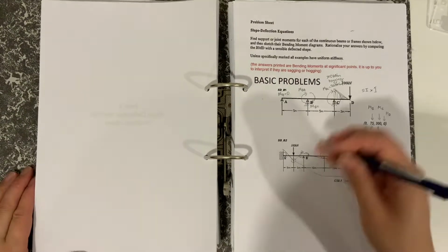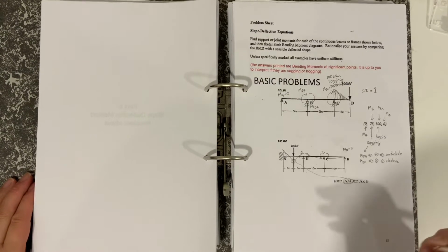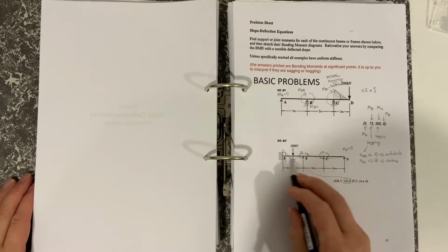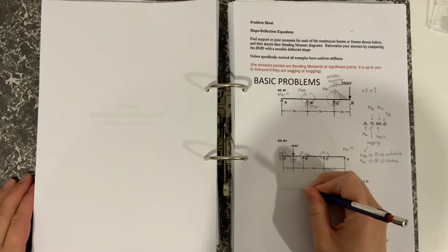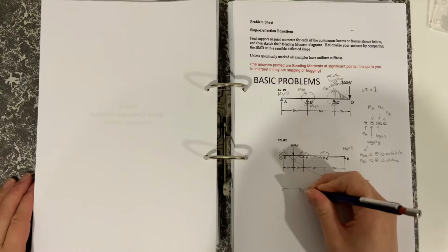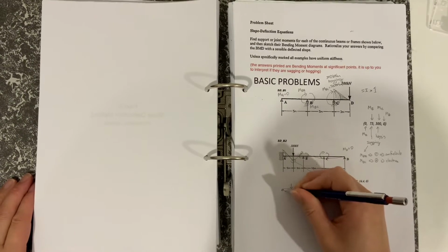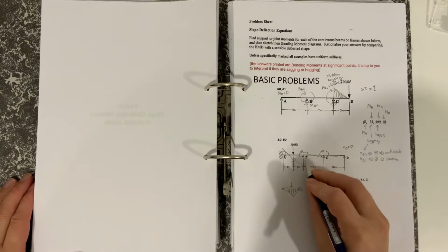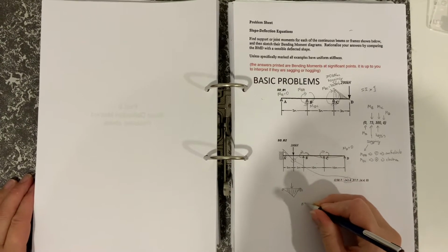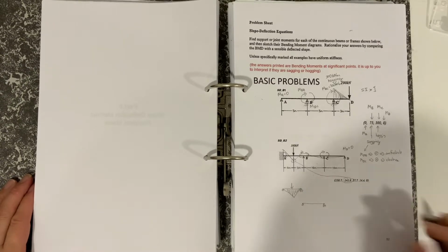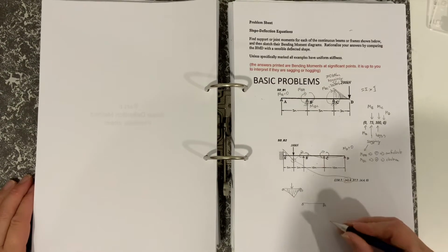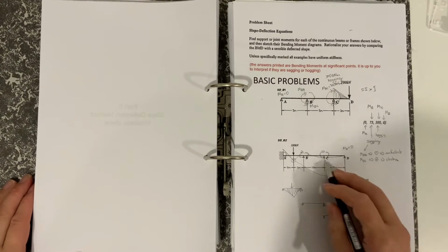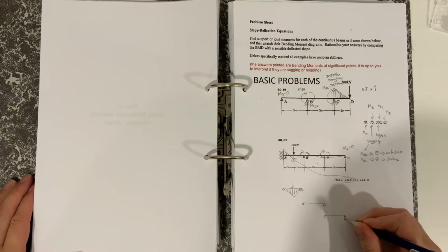So when you do the calculation, it might say what is the active bending moment diagram. So the active bending moment diagram for AB is, so that would be the active bending moment diagram for AB, and the active bending moment diagram for BC, which I'll draw a bit lower, would be 0 because there's no load acting on BC, and the active bending moment diagram acting on CD would also be 0 because there's no load on it.